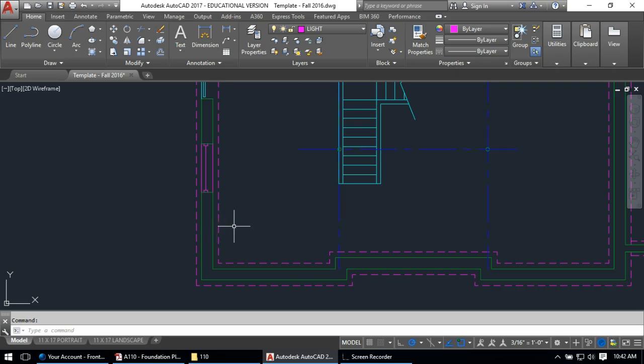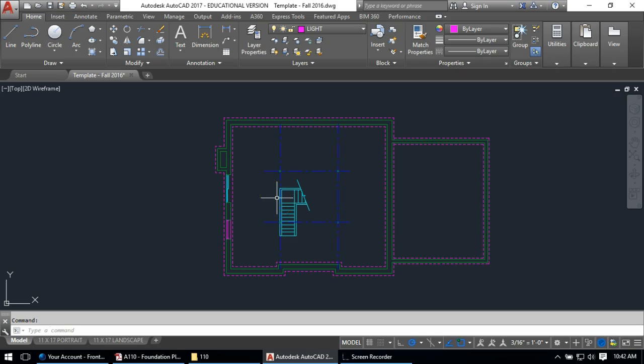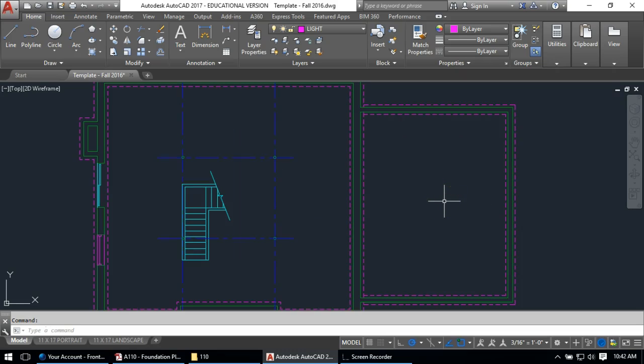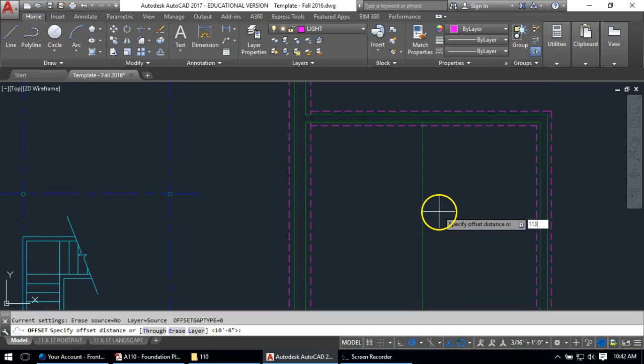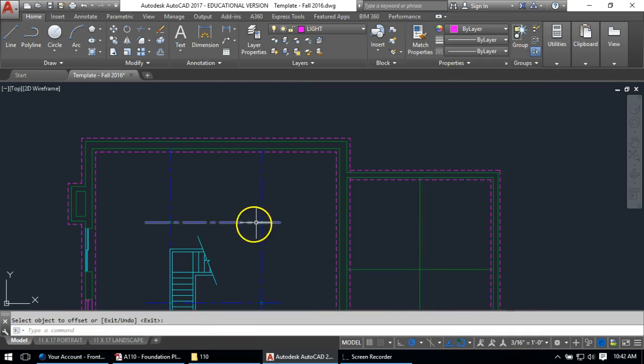So we're getting near to drawing. We've got a few more things to draw here. One of the things I noticed, we have put a column out here. I've got to put footings around these guys as well, but let me finish the column first. Looks like this column over here is going to be 10 foot 8 in. It's going to offset 10 foot 8 that way. That'll be the center point, and it comes down 13 foot 4 from the top. Just like before, that's the center line of that column.